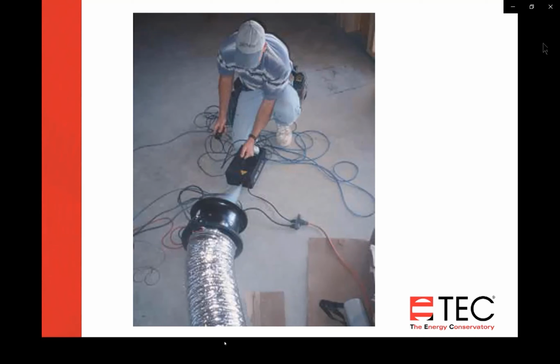What I've heard is that theatrical smoke generators, the more expensive ones, will produce too much fog for testing ductwork, and it will fill up the basement or the attic full of smoke before you get a chance to find the leak. So usually the inexpensive ones that you can get at a party supply store are adequate and can aid in helping you find the leaks.